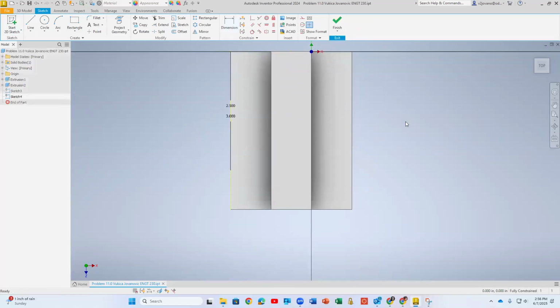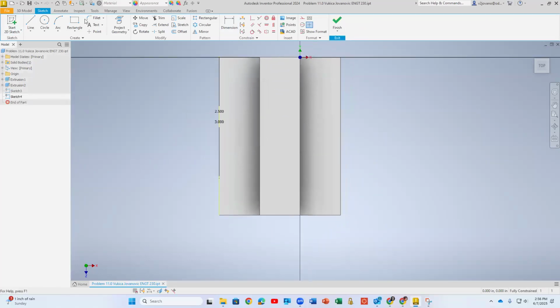I think they want to show us how to create another sketch with multiple points. So again, here I will prepare first. I will select this line, project geometry. I will convert this to invisible. So you see, by using project geometry and this, I can create another point, and I will put a point anywhere outside.